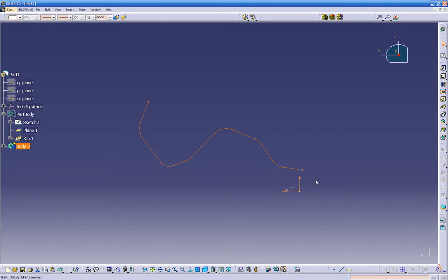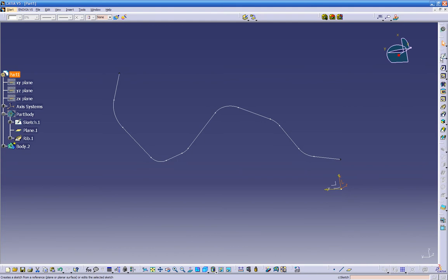So now let's create on this direction right here another curve, which is gonna be the Z and X plane. So let's go this plane right here. So XZ is the same as this XZ. So here, let's create another sketch.